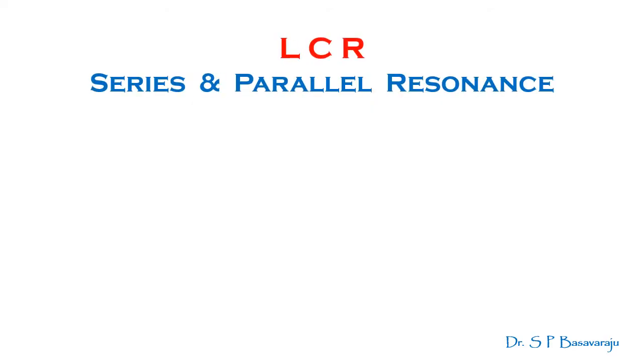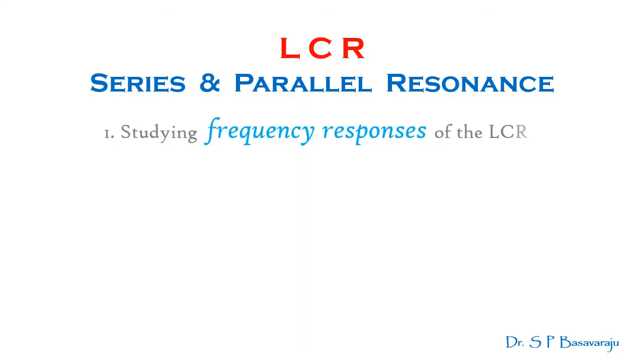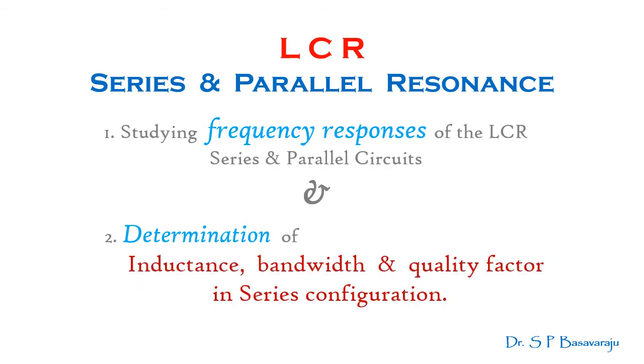As a recap from your regular class performance, you can recall that to begin with, you had built up the LCR series and parallel circuits and then studied their frequency responses by feeding an AC into the circuits. Afterwards, from the graphical plots, you got the two resonance curves from which you had evaluated the inductance values of the inductor. Then from the series resonance curve, you went on to evaluate the bandwidth and then the quality factor of the resonance. Now you will be quickly going through all these like a revision visually.